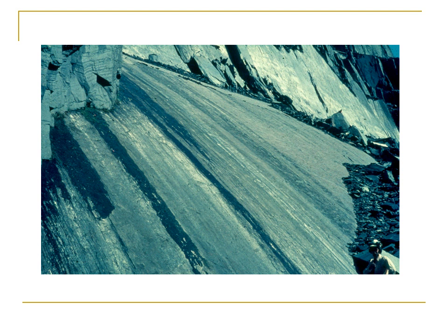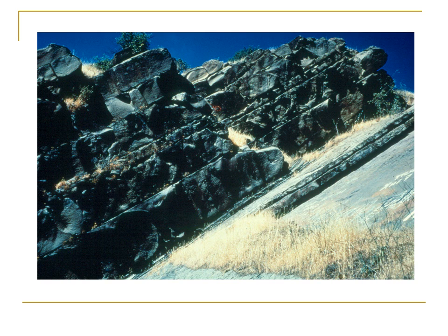Here's a view of what's left after rock has slid along a single plane. So you see a smooth surface along which rock has slid, and you see some of the debris collecting at the toe on the right. Here's another case where part of the slope has already previously failed, and this potential sliding mass here is what's left and has enough stability to still be standing in the slope, but it has the potential to slide as well, slipping along that plane surface that the adjacent rock slid along.